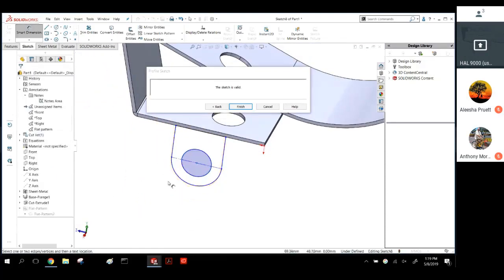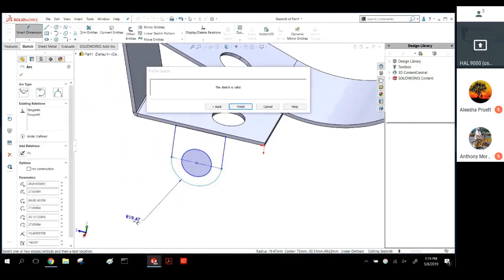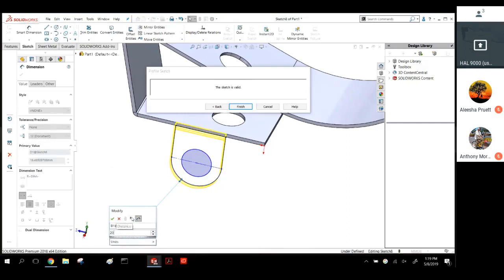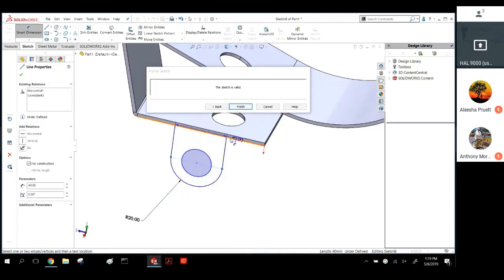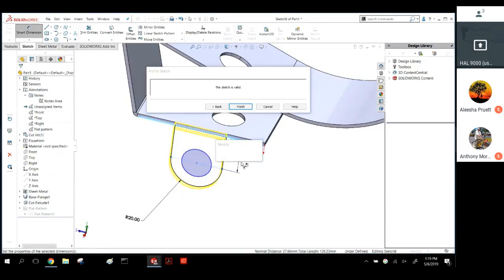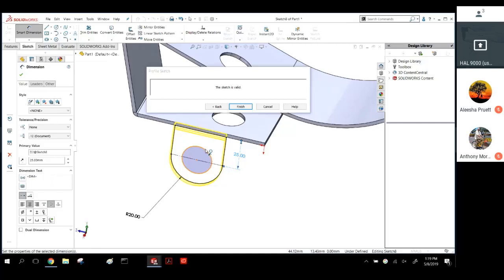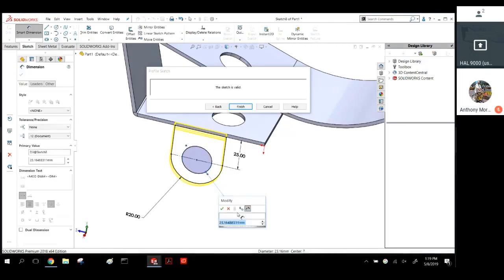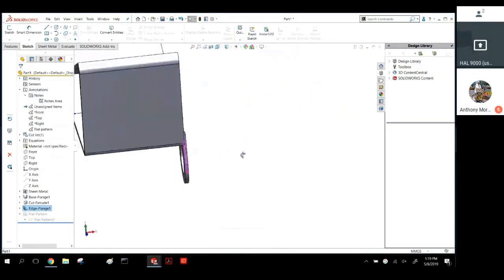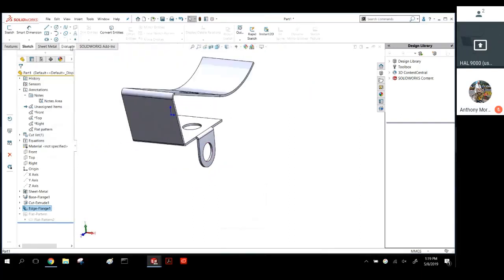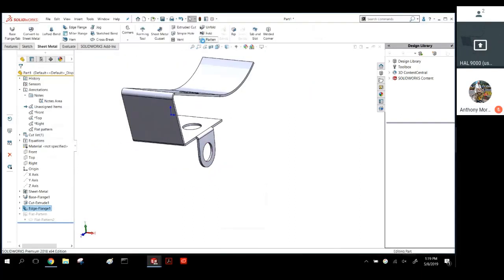I just really need to start putting some dimensions on this thing. How far I want it to come down. How big this hole is. You see that you can do nested contours. That is fine. And when I finish, it fills in that whole shape that I did with a tab. Of course, this will flatten just like the rest of it.